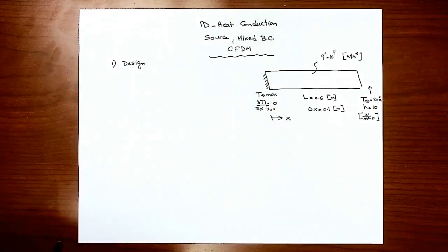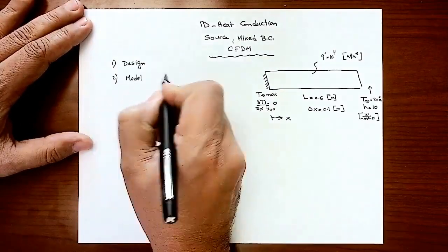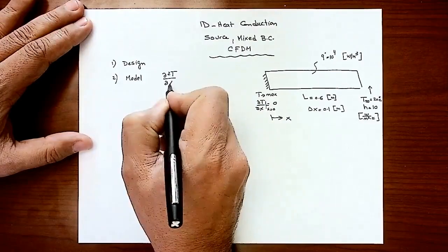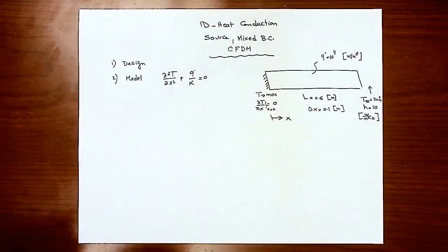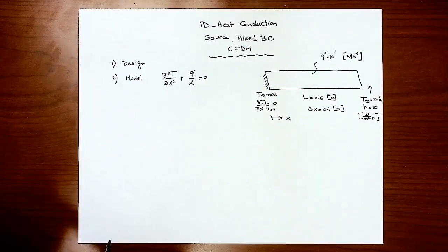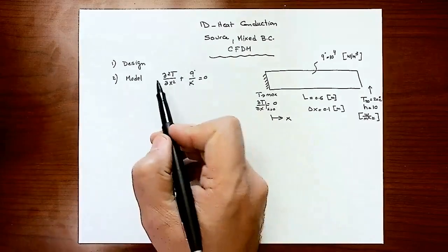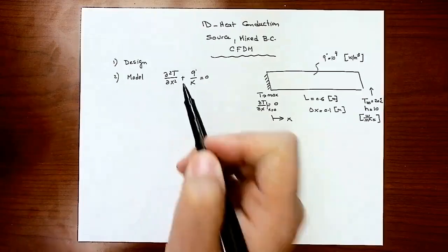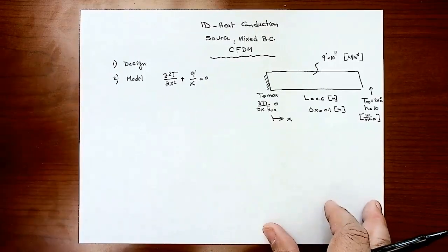Now, what's the governing equation? What's the model that we will apply? It's still the heat diffusion equation simplified to these two terms. It's a one-dimension problem, so X and Y and Z are gone, and it's a steady-state problem. So the right-hand side of the equation, the energy stored, is gone, and what remains is just the second gradient of temperature relative to X and the heat source. And remember, K is supposed to be on this side, so we divide by K. That's why K is coming under the Q dot. So that's my model, right? Then we did the simplification.